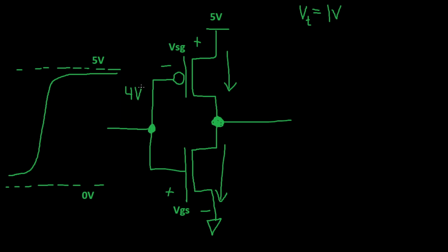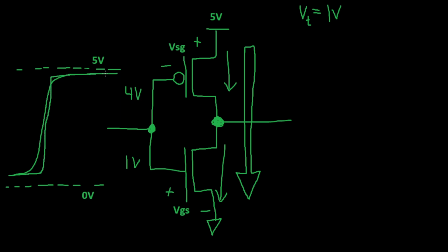And in this case, all the way from 4 volts down to 1 volt, we're going to see that current can flow through both of these devices, and we get something called shoot-through current. And that's current that flows all the way down through both devices straight to ground. And this can be damaging current. You don't want this to happen in a CMOS device. And this is why datasheets are going to specify that you need a very fast transition from low to high for a CMOS device, rather than a slow transition.